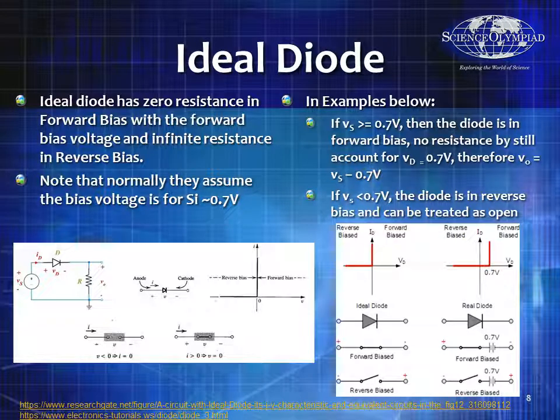However, it'll be slightly offset by the forward bias voltage. If you look at the lower right-hand side, the red line shows you an ideal diode, but a real diode goes sort of similar, offset by the forward bias voltage, which is about 0.7 volts for a silicon diode.